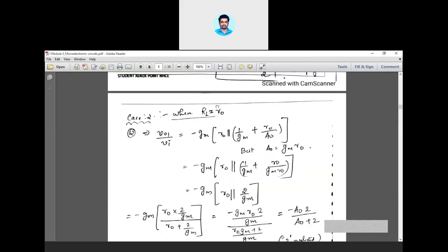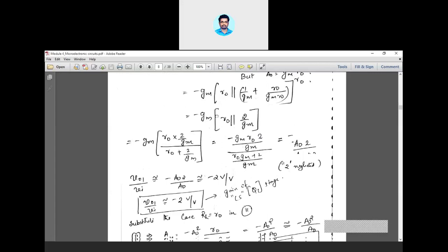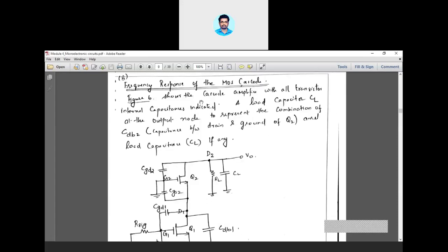You know what frequency response means, isn't it? What do you mean by frequency response? Frequency response is the plot of gain versus frequency, that is, how the gain of the amplifier varies with respect to frequency. So you should give a proper input frequency so that, based upon that frequency, you will get the gain at the output. If you increase the frequency to a larger value, your gain will decrease.